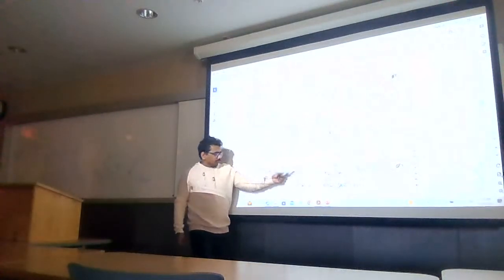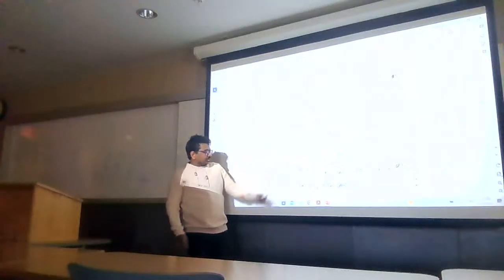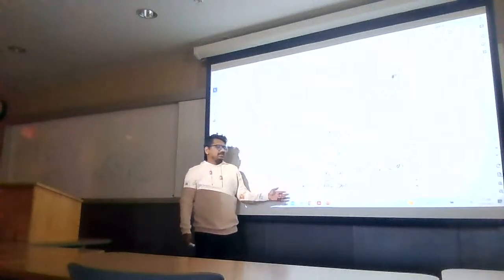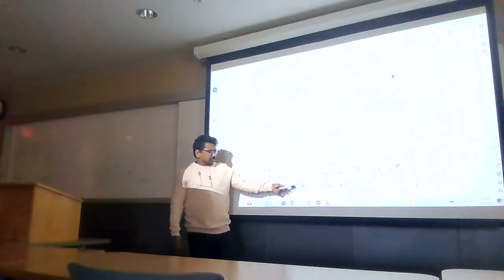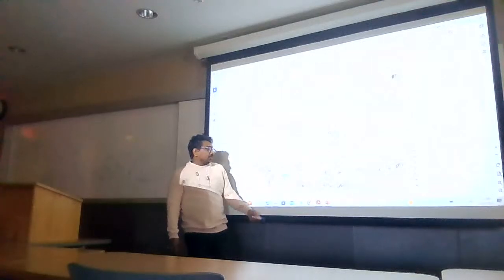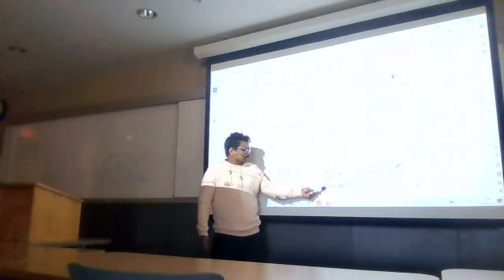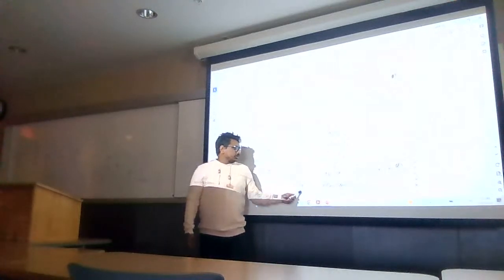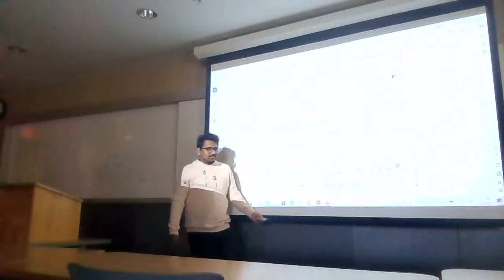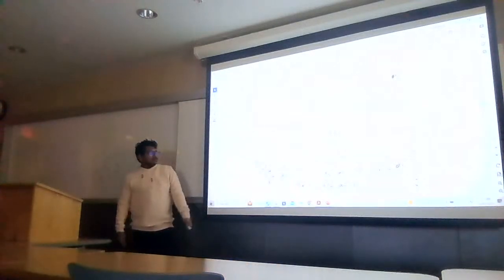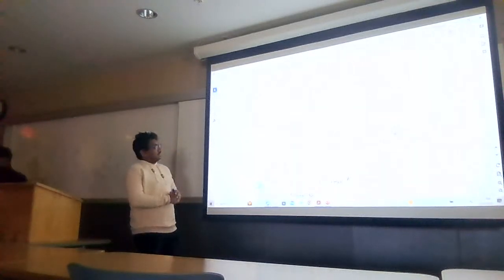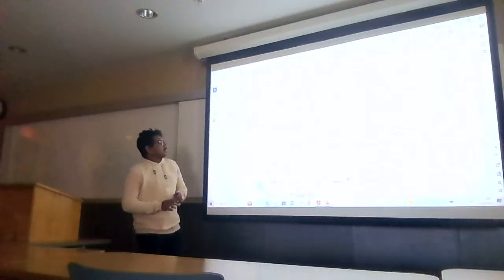There are also some more common expressions for GM, and this one is very popular. Circuit designers use this expression too many times. If you assume 2 mu n Cox W over L is constant, my GM is proportional to the square root of ID. So can you go down a little bit? Yeah. So by taking all of these assumptions, let's design our first amplifier.